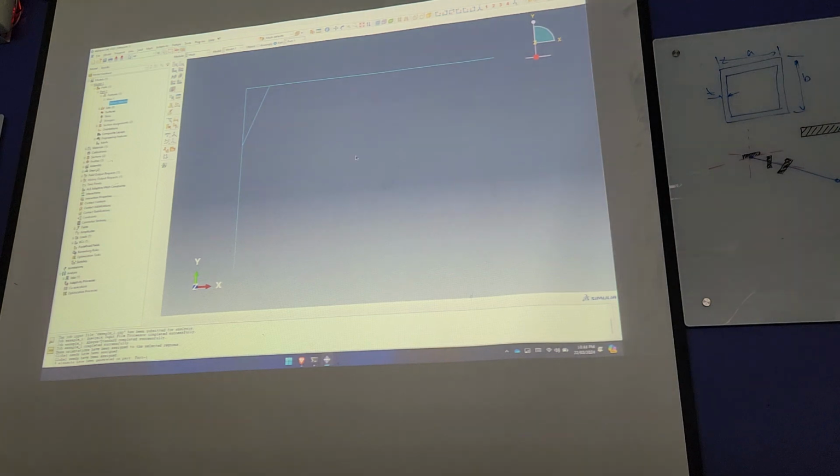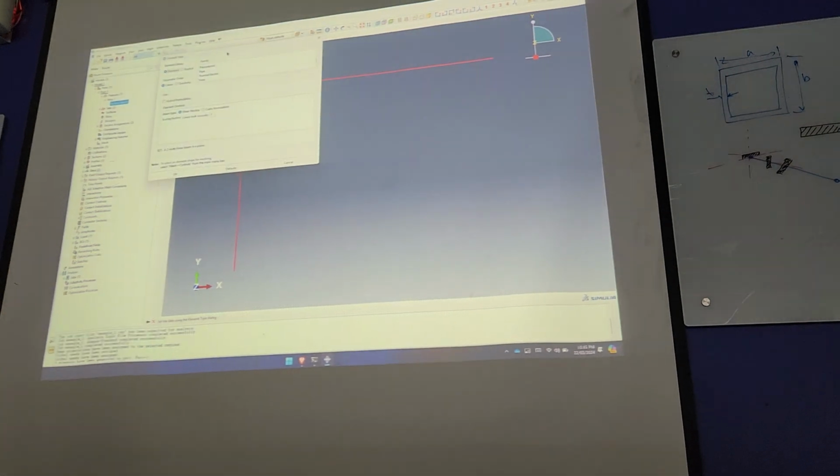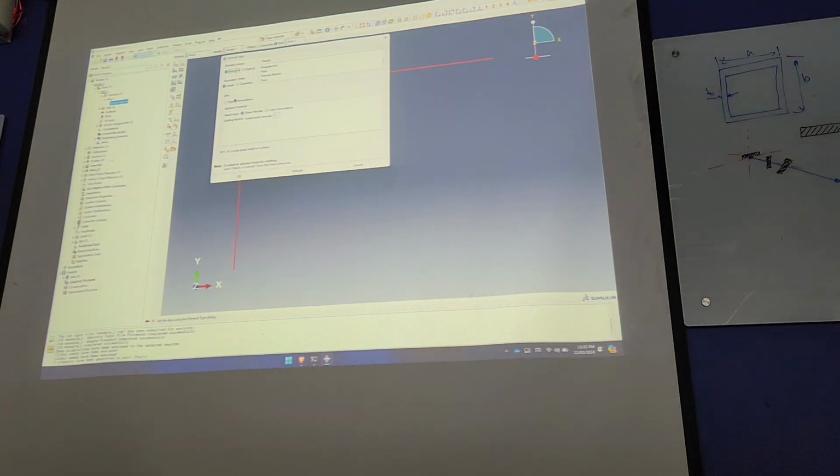So we click mesh, and then we need to make sure that we have correct elements assigned. Yeah? So we go here, assign element type, click on that, and we choose our beams. Done. And then you go and find your beam. Here it is. Now, remember when we talked about element types?